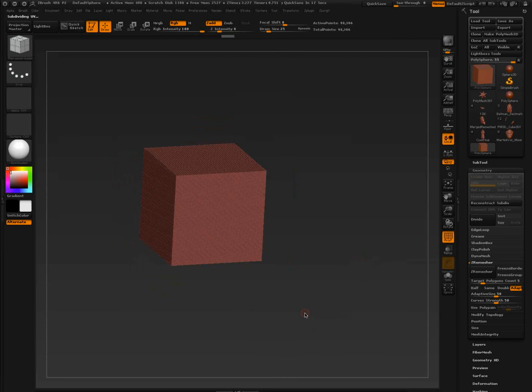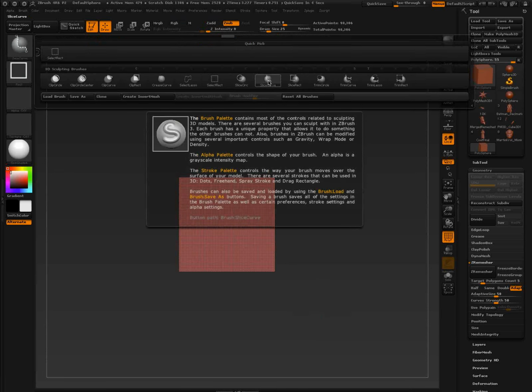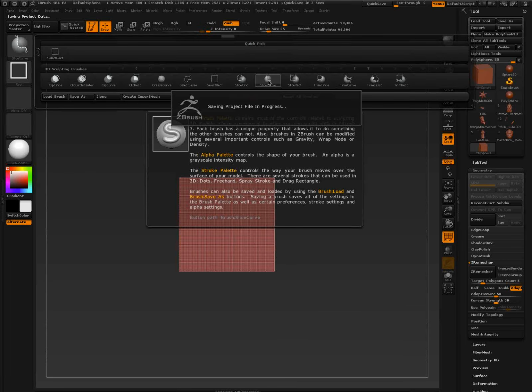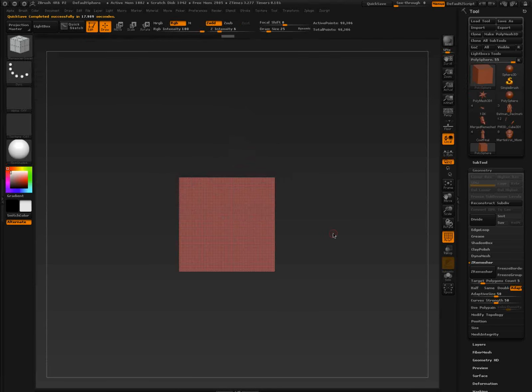All right, so now let's try doing a brush. Okay, let's use our slice brush. So I'm going to hold down the Control and Shift key. Now some of those advanced users out there, when you're holding the Control and Shift key, you can see I get different brushes. There's different things happening with the brush. So there's different controls that you have. You have your clipping brush, you have your slicing brushes, you have the new trim brushes. And by the way, now all these brushes will work with hidden geometry and non-hidden geometry. So that's very important to understand. It made my workflow so much better. There's so many cool things that I was able to do now, and I'll pull up some examples.